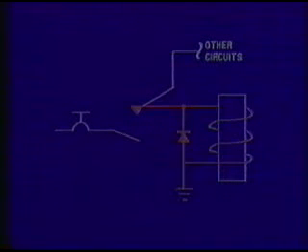Now opening the switch, the field collapsing induces a voltage. This illustration shows how the now reversed polarity backs up. Since it is backing up, this end is negative. It cannot jump through the open switch, but does want to flow into the adjoining circuitry. To prevent this, the diode, because of its polarity positioning, detects the reversed polarity spike and routes it harmlessly to ground.